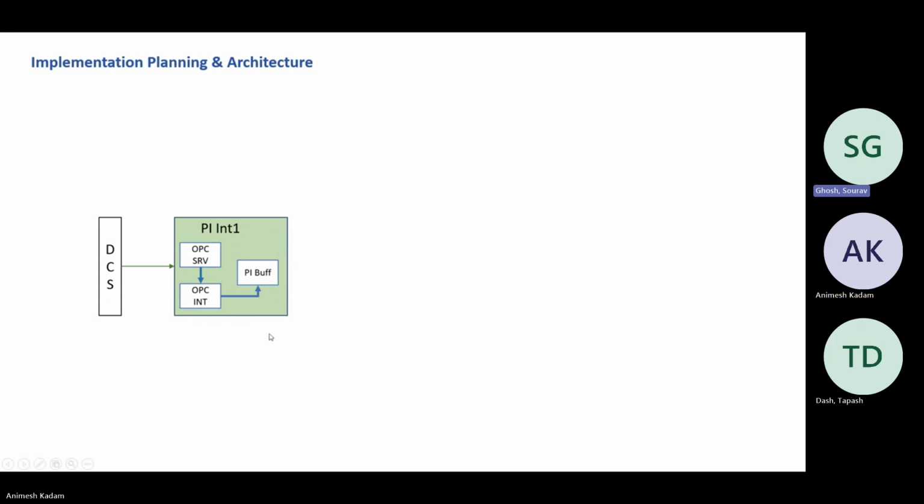Okay. So this DCOM setting should be between the OPC server and my Pi interface, Pi node, right? Right. If it is on a different machine. Yeah. If it is on the same machine, no DCOM is required. DCOM is basically a distributed communication thing. So if it is on the same system, you don't need DCOM.